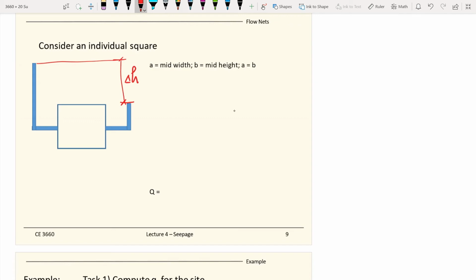It has a head going through the individual elements. So before entering, you have some head drops. That's kind of like going through two equipotential lines. Because if you understand this, if this is one of the grid elements of the flow net, so these are your equipotential lines, and these are your flow lines.